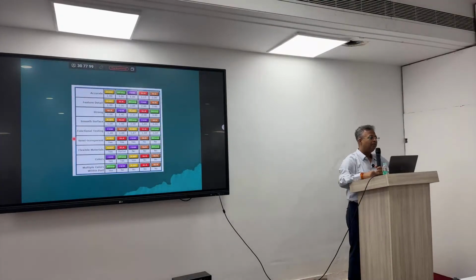Okay, then we have some other plastic processes also, like what is called polyjet printing. This polyjet printing is also being taken over by FDM now, in specific systems. There is another machine called Objet Connex which was similar to it, and then SLA, stereolithography, FDM and SLA. So for various features we are able to compare these processes, like in terms of accuracy, feature details, strength, surface quality, functionality, whether they are transparent or not, flexible or not, colored or not.